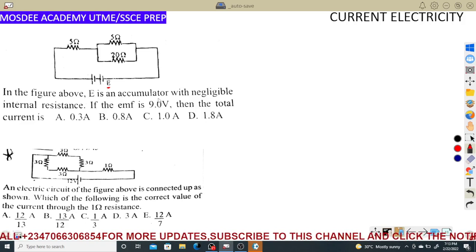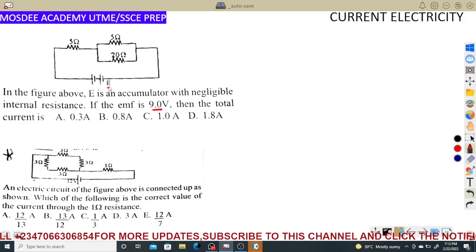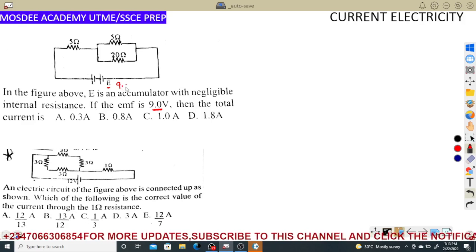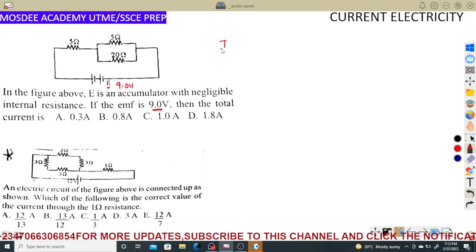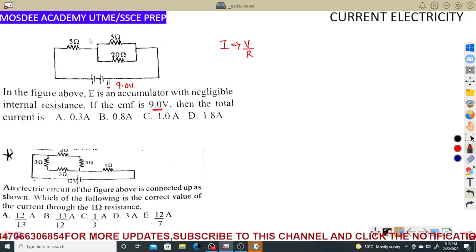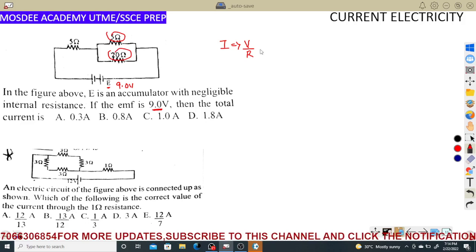Now, E is an accumulator with negligible internal resistance. If the EMF is 9, the total amount of 9.0 volts was passed through this. So we can write 9.0 volts. So the total current, from Ohm's law, I is equal to V over R. So what's the total V? 9. We need to get the total R. What did I tell you about this? This and these are in parallel. Let's get the total R.